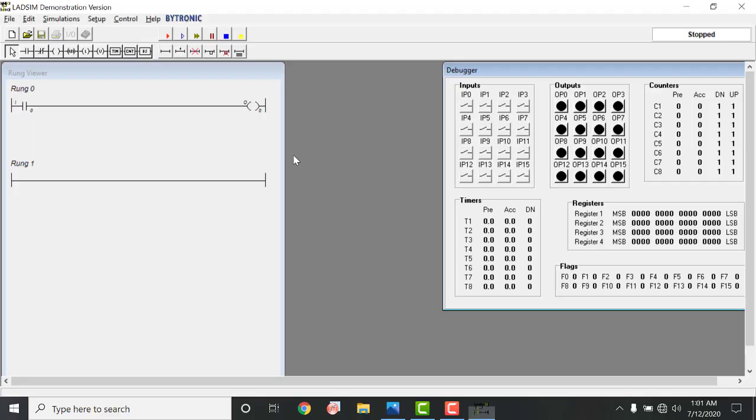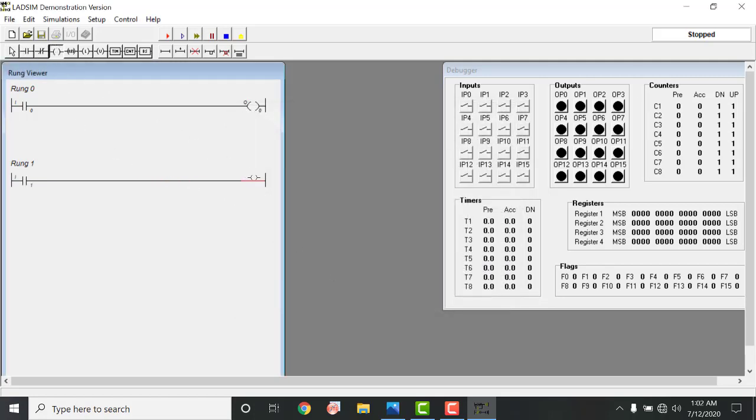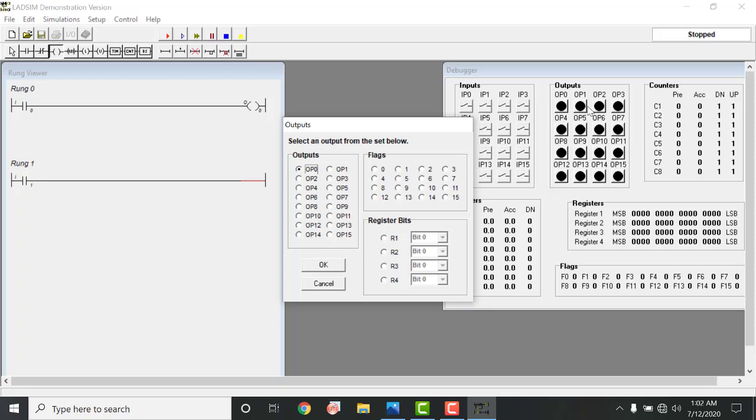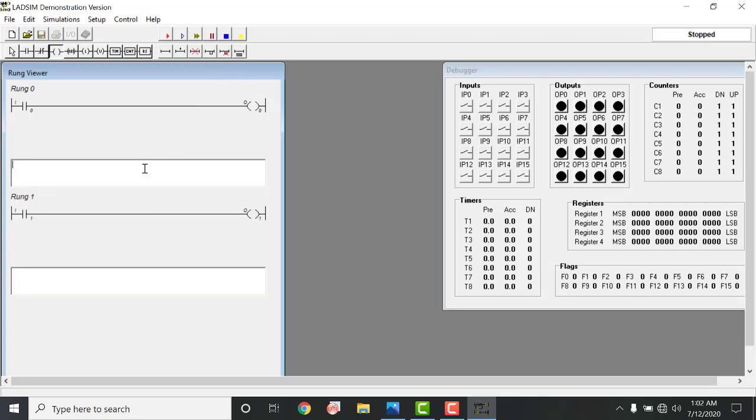So we have to design another open switch for that, and this time input 1, because we have already provided input 0 and assigned it to the conveyor belt motor. So input 1 will be assigned to this infrared sensor. Okay, and this output over here to show it, we use output 1.